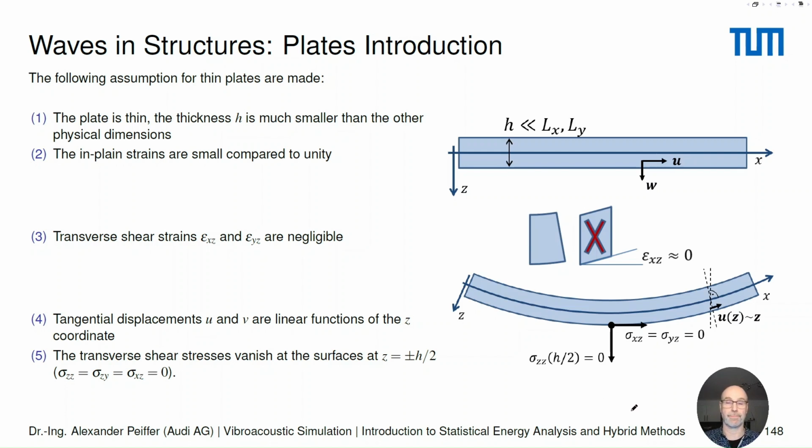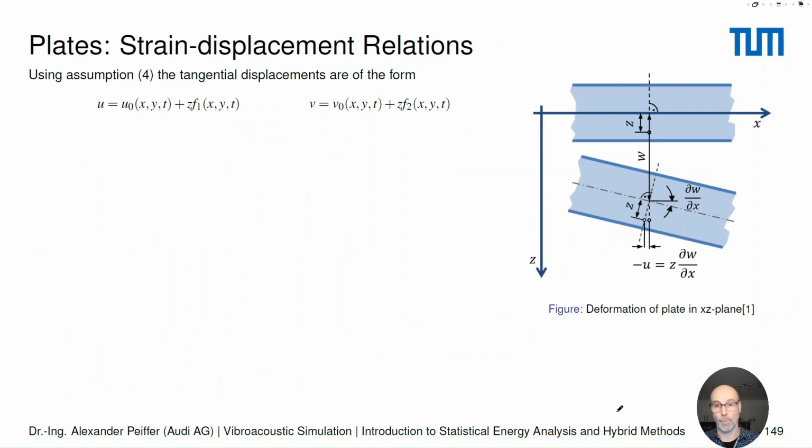Good. So let's come to the next step. When we talk about plates and also shells, the physics is described by using only the displacement of the center plane. That's the middle plane of our plate. All other quantities, and especially the dependency of those quantities in z, are derived from simple formulas.